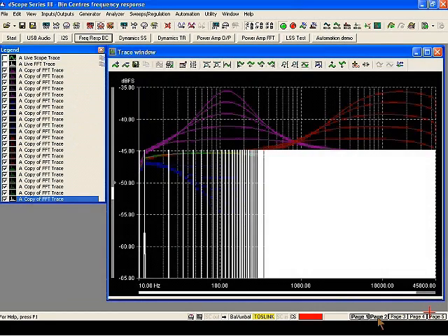Before we do that, I'm just going to show you what this bin center stimulus looks like if we use a very large FFT size. So in this case I used a 64K FFT, and you can see that there are a series of discrete sinusoidal components at all of these individual tone frequencies. On my logarithmic x-axis scale, these become apparently more densely packed together as we go up in frequency. That is simply because these tone components have an equal spacing on a linear scale. So on my log scale, which we as audio engineers quite often use, these appear to become more compressed, or closer together I should say, to avoid any audio terminology ambiguity there.